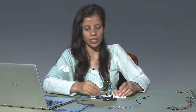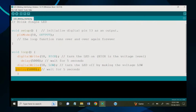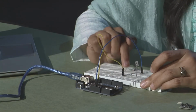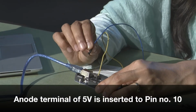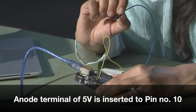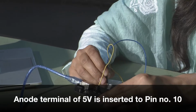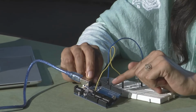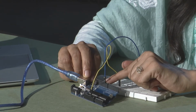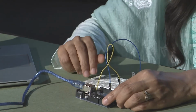So, let me first show you the hardware part we are going to use as it is. The anode terminal I am now taking from this 5 volt and inserting it into pin number 10. You can see I have used the 8, 9 and 10 terminals. Now my connection must be ready, and we can start transferring our code by inserting this wire.